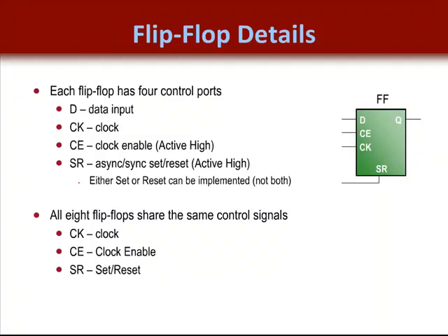There is no local inversion for either of the clock enable or the set reset ports. You also need to know that the set reset port can be programmed as either a set or reset, not both. Unlike older architectures, there is not a separate set and reset port available on the flip-flop. So if you want both, either the set or the reset functionality will have to be generated from a LUT and thus be a synchronous set or reset.